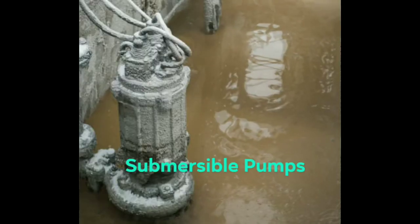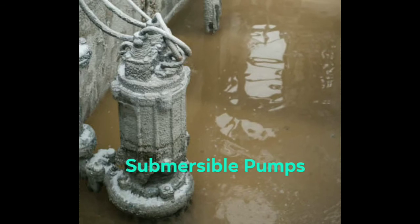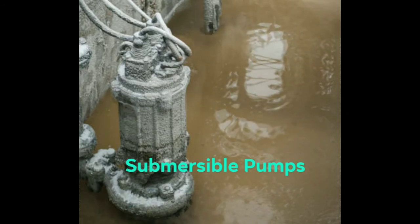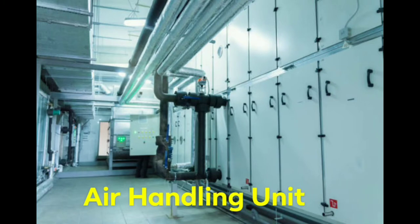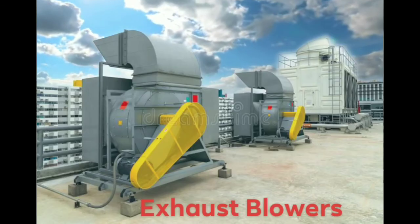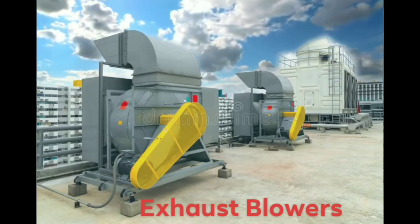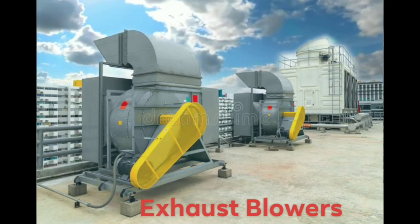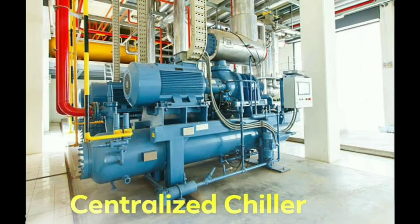Wye-Delta Electric Motor Control is commonly used in high-powered submersible pumps for the flood controls. It is also widely used in air handling units for centralized building air conditioning systems. Another of its common applications is the exhaust blowers used for the air out and exhaust systems. It is also used for the conventionally driven centralized chiller for building air conditioning systems.